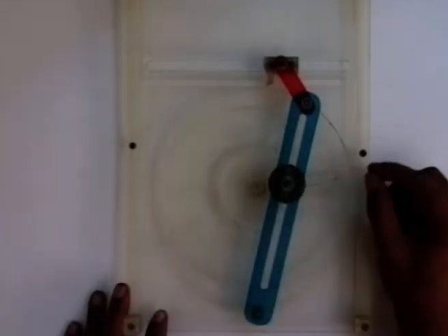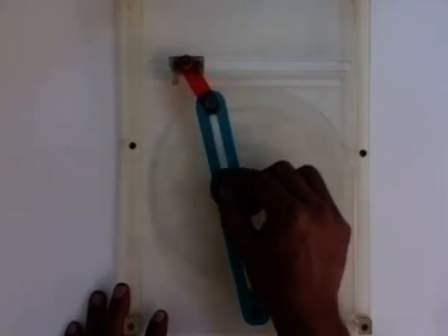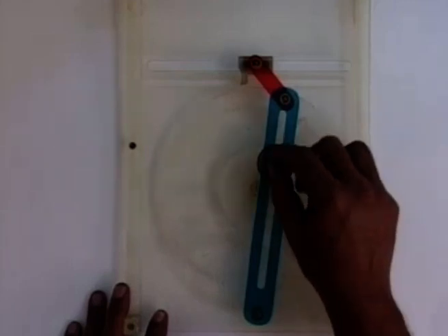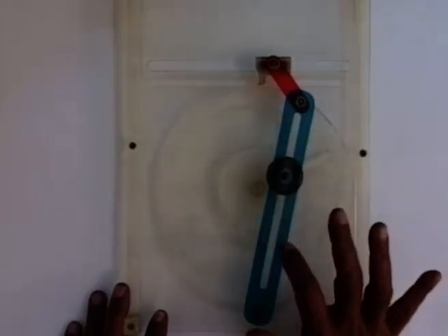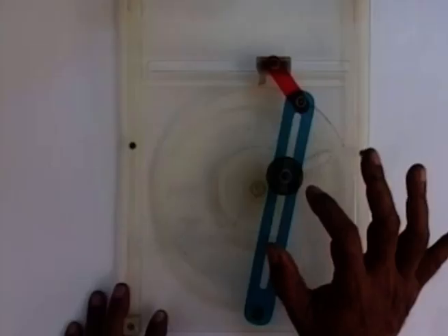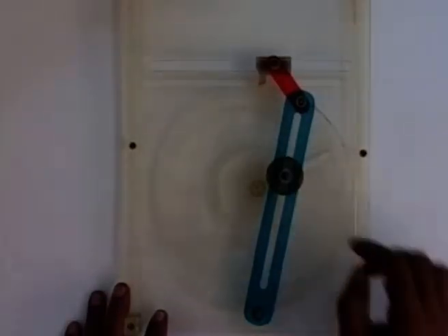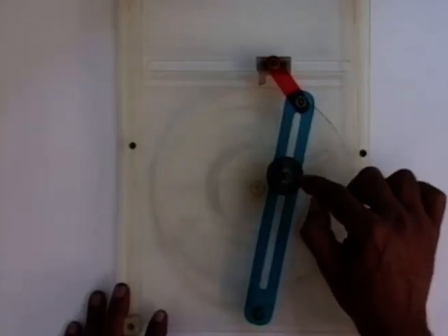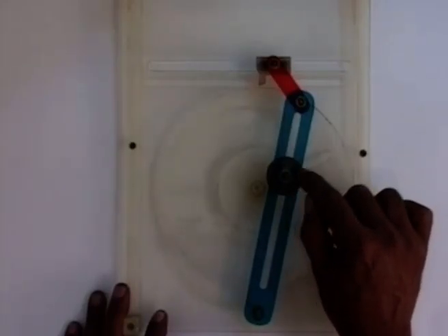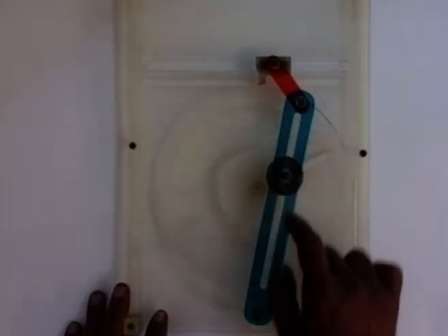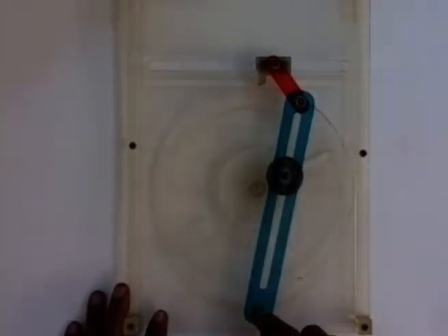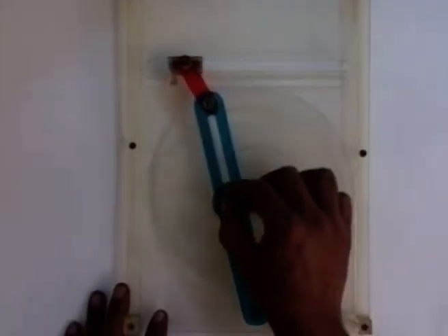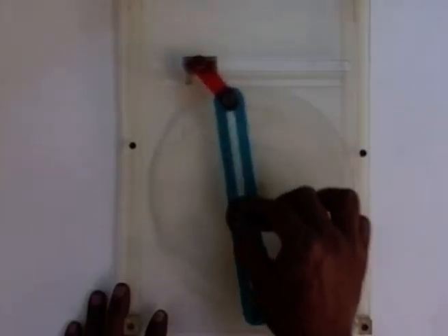So, A2, A3 always remain coincident, but A4, A2 and A3, they have relative movement. A4 is a point belonging to this slotted lever. Now so that is the concept of coincident points. A2 and A3 always remain coincident because this is the block center where body 3 is hinged to body 2. A4 is a coincident point belonging to body 4, which is going in a circle with this point as center and this as radius, whereas A2 and A3 are going on a different circle. So they always do not remain coincident.